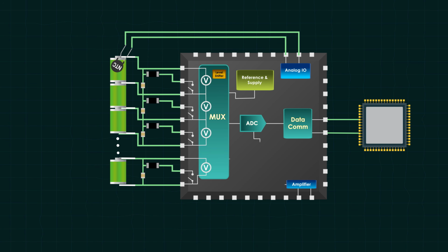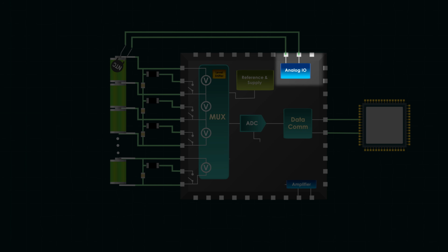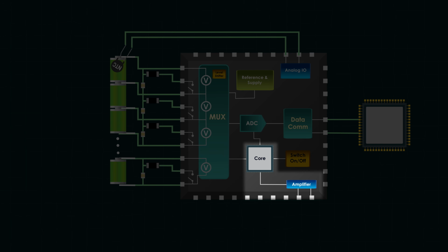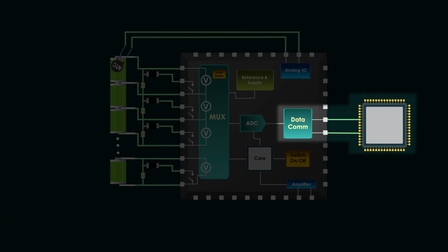So it has all the special circuits inside. One group continuously checks voltage like a voltage inspector, and another monitors temperatures. All these measurements get amplified and calibrated, precise down to the millivolt level. Then these analog signals hand over the data to the ADC department, which converts the values into digital signals with high precision. Many BMS ICs use 12-bit, 14-bit, even 16-bit ADCs for fine resolution. Finally, this data is packaged and sent to the microcontroller.